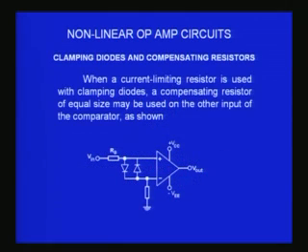There is also another important consideration that you should take into account. We know that even though an op amp is a wonderful device, almost an ideal device, it is not quite ideal, in the sense that it does have a difference in the two input bias currents, there is an offset voltage, and several other things that come because of the not-so-ideal situation. So you would find there are two input terminals and the voltage is compared between these two terminals. The two voltages should correspond precisely to what we set with reference to that. If not, then it will become more complicated.